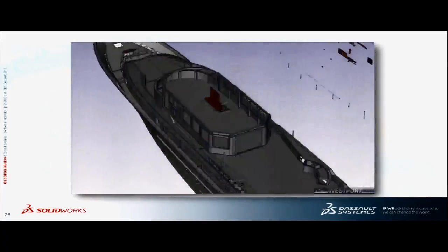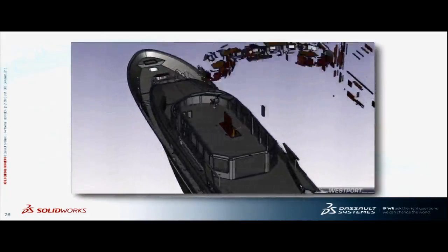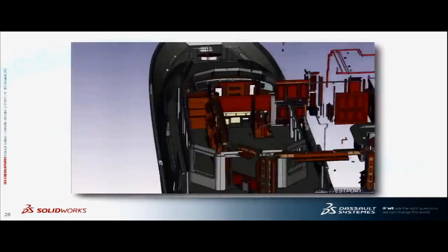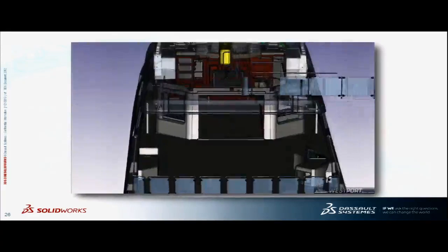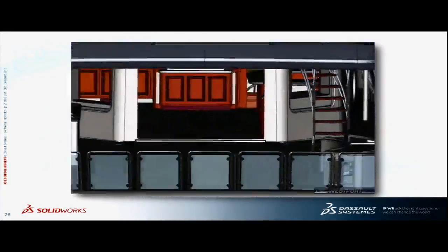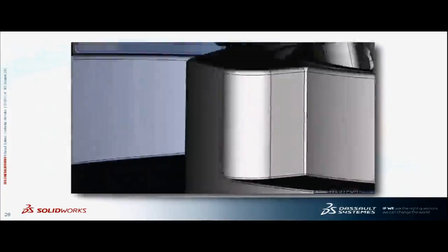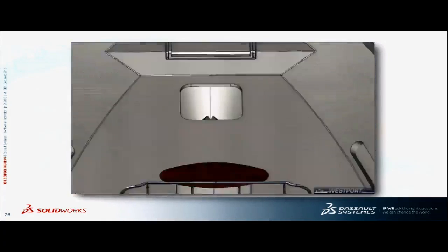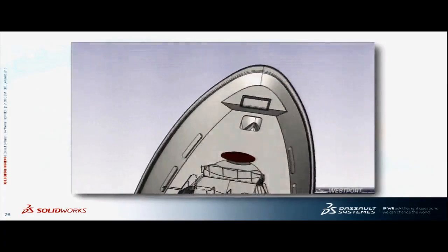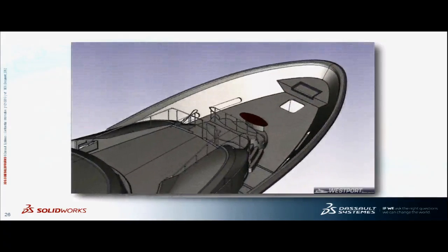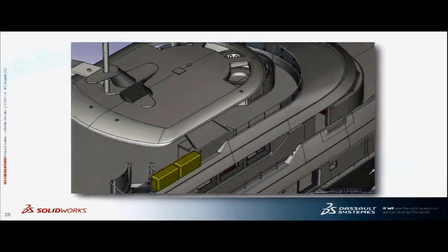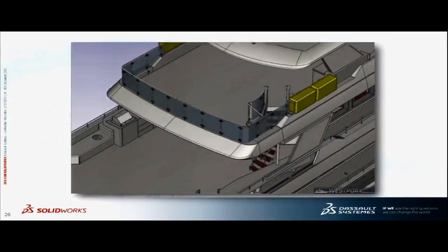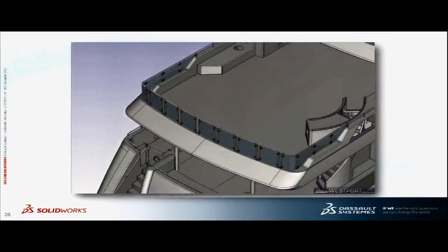What they've done is they've simply animated, given a timeline saying, at this particular point, that subassembly, we know where the initial starting point is, we know where the final position is. And Composer figures out how to get it from that point to that point. Basically, all we did for this was to say, all right, this subassembly, you go back to your original position. This subassembly, go back to your original position, and so on until it's done. And it's just one step after another.